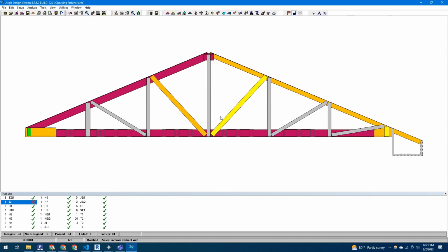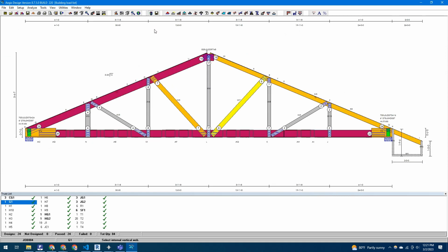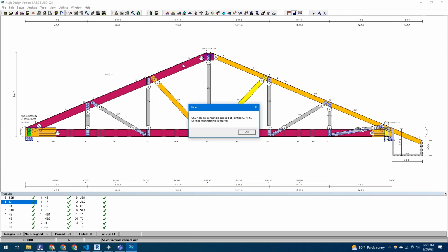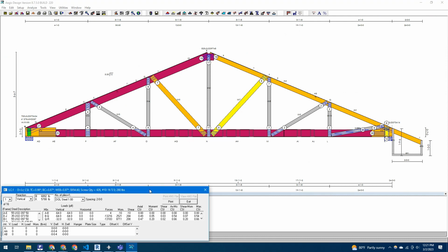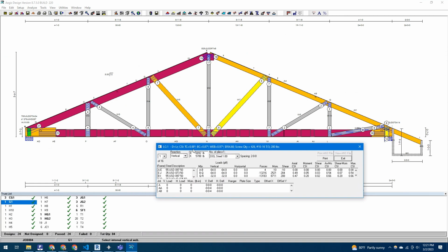All right. Click OK. Hit save, that's why it's still X. Yeah, there we go. Okay. Oh, it passed? How did you know it passed? There weren't any bright red pieces anywhere. So this maroon color is 12 gauge. Dark maroon passes. Bright red is failure. I don't know why, but somebody made the choice that the 12 gauge has that dark red, which is the color they spray paint the ends of it.